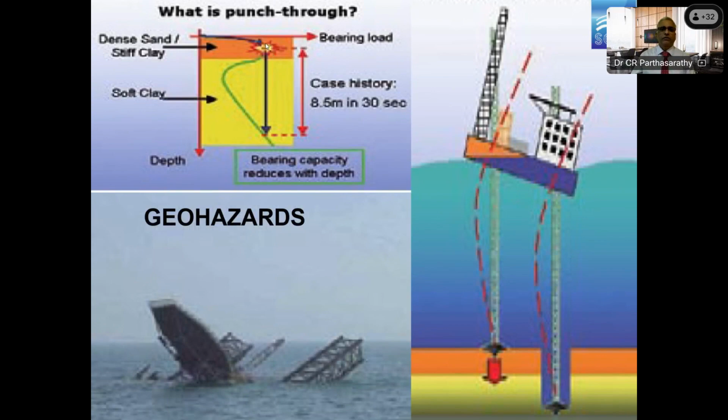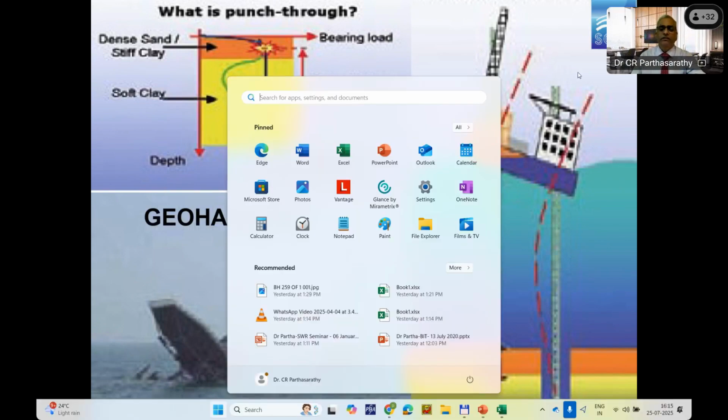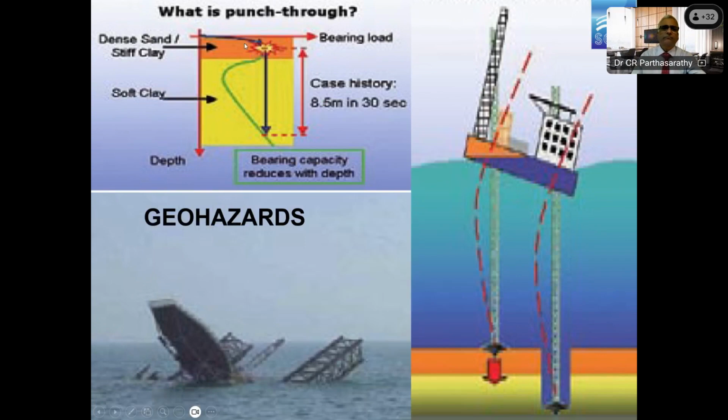That occurs from the presence of a desiccated strong layer underlain by a weak layer. And these desiccated layers can exist at the surface or at a certain depth. So what is this desiccated layer? Perhaps that could be the top of the seabed several thousands of years before. So with repeated fluctuation in the water depth, this desiccated layer becomes very strong, very hard,